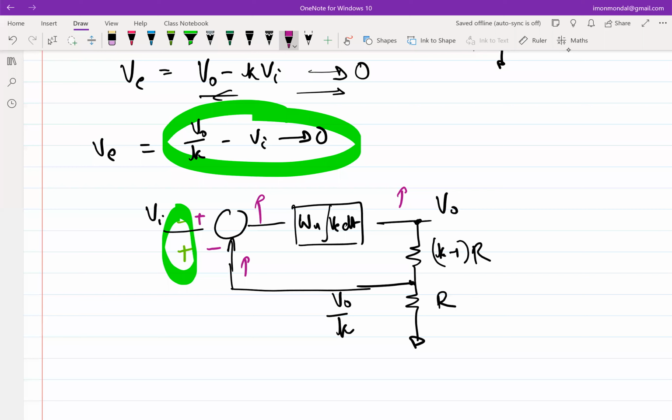this will increase. If this increases, the integrator is driving the output to a higher value, in the positive direction, which means that I am in a positive feedback loop, right? It's not trying to negate any change, it's trying to amplify the change. It's reinforcing the change. The integrator is operating in completely the opposite way that I want it to.